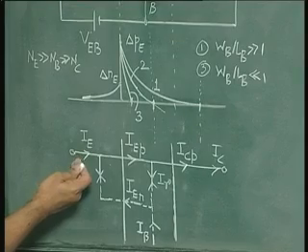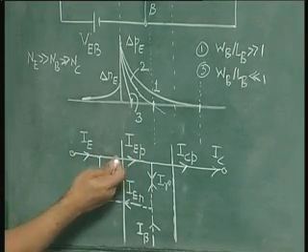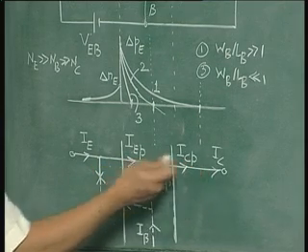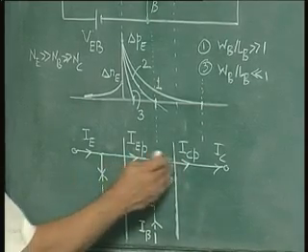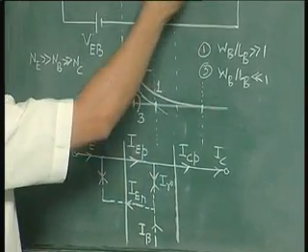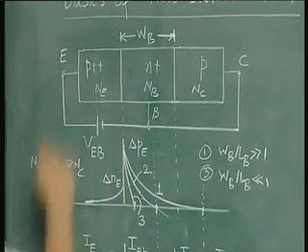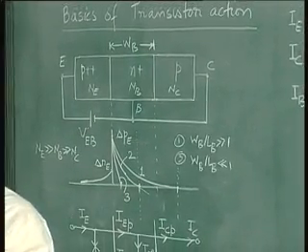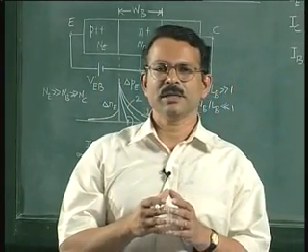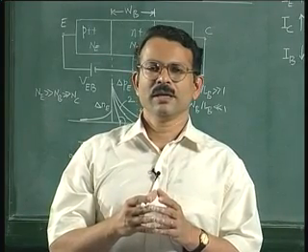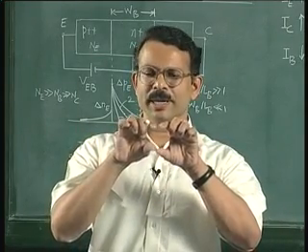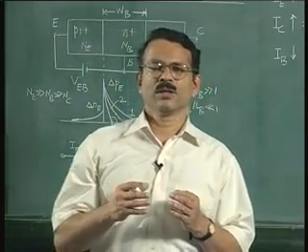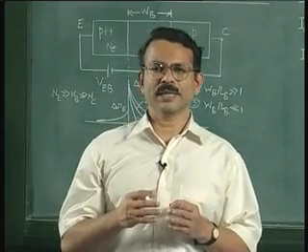Anyway, the emitter is injecting the current. Now part of the hole current that is injected is reaching this contact. It is collecting the current that is remaining after moving through the base. That is why this contact is called the collector. It is collecting the holes which do not recombine in the base, and this is the base contact, because if you recall the diagram that we had shown in the previous lecture in the historical development, the emitter and collector contacts were on a semiconductor substrate or a base. That is why that third terminal apart from emitter and collector came to be called a base.